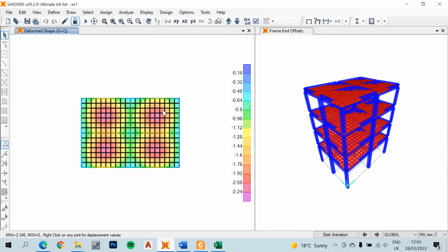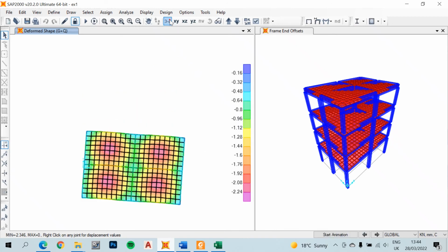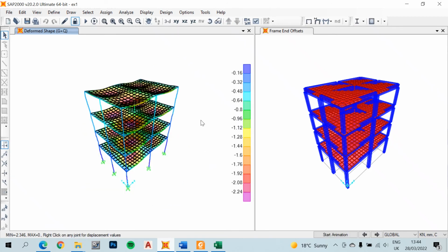I think it's the reason why you have very small deflection. This is like -2. It's because you saw the slab thickness is 14 centimeter, and for such a building I think 14 centimeter is actually a large number. So yeah, there are many things you can check from using these properties.